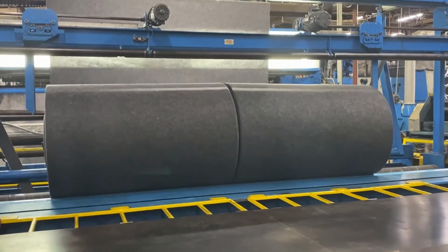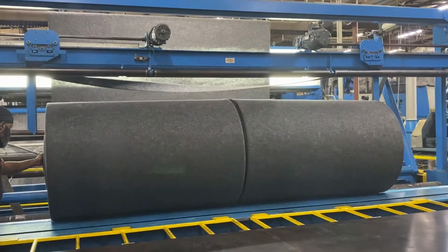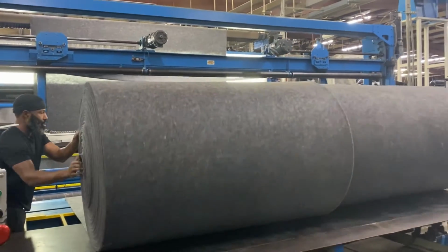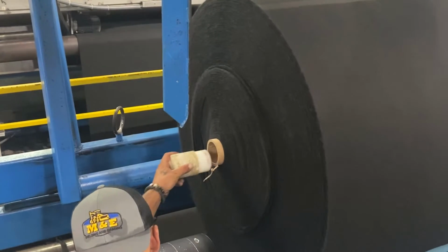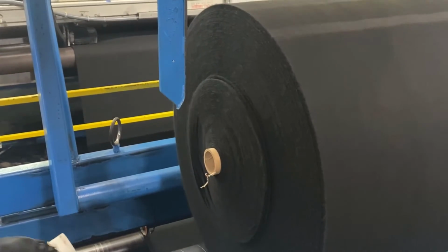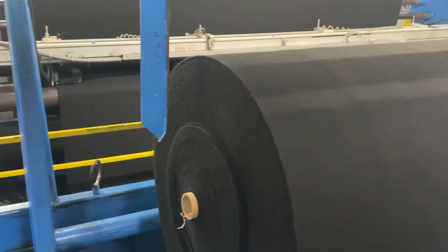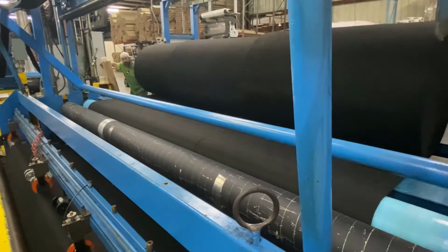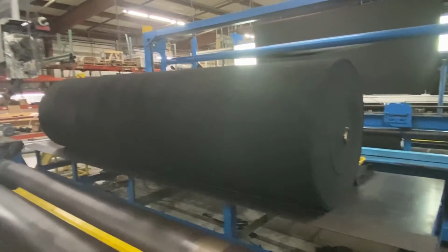Once the roll reaches the desired set point length, the winder will stop and it will be time to doff, or remove, the roll from the winder. The first step is to disengage the core guiders and raise the lay-down roll. Then use the doffing bar to push the roll out of the winder and onto the doffing table, which has a built-in scale.